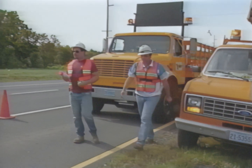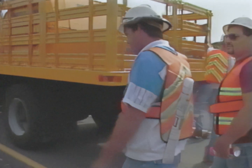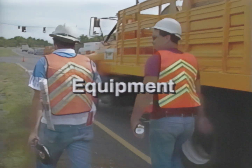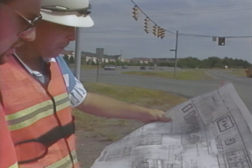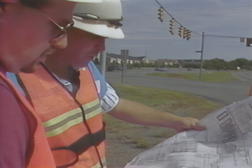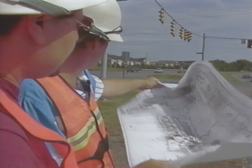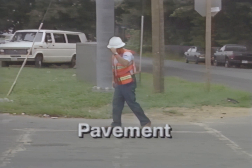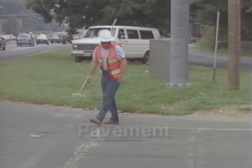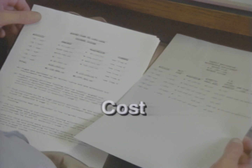When basing your selection on installation, 3 things should be taken into consideration. First, existing equipment. To keep costs down, examine the equipment currently at the site. For example, if a suitable pole is already at the location, you might choose a radar or ultrasonic detector over a loop detector. Second, pavement. The type of pavement and its condition can influence your detector selection. Third, cost. Consider the life cycle cost of the detector.